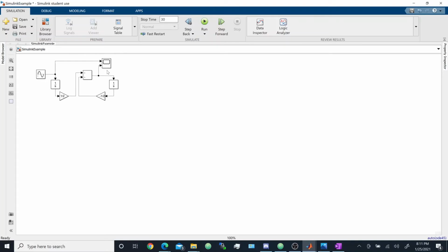We should see exponentials to charge up the capacitor, because if we look, ooh, that's not great. Oh, I know why. So if you want to change up your pulses, you go into the pulse generator. It's because we didn't give it enough time to actually charge up. So right now the period is 10 seconds.